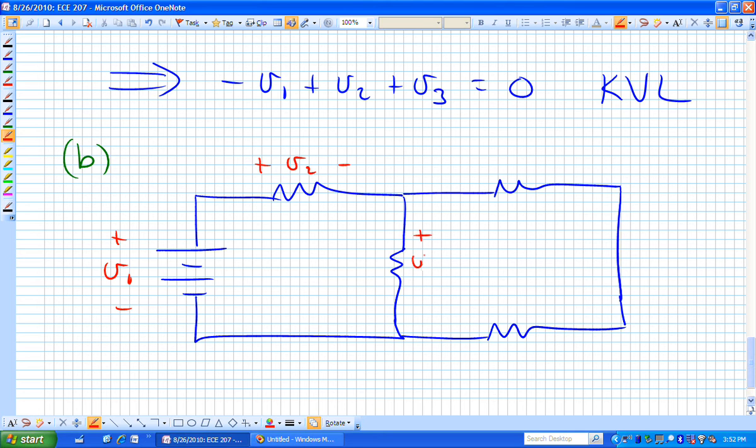Let's initially go down and say that resistor, the vertical resistor, is V sub 3. Let's say the next resistor after the vertical resistor and up top on the right, let's say that's V sub 4 from left to right, positive to negative. And now, because of what we know maybe we will encounter when we go around the loop, let's just label V sub 5 plus to minus from right to left. We wouldn't have had to, but if we need to call V sub 5 something, I'm just going to arbitrarily assign that voltage orientation or label to that particular element.